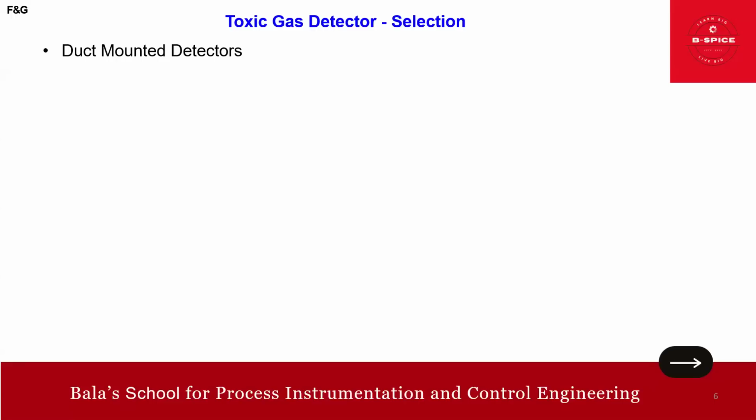So the duct mounted gas detector shall be provided complete with an integrated test gas facility. What for? To allow validation and calibration without removing the detector from the duct, even when the HVAC system is in operation. That is the point. So calibration of the duct mounted detector shall be possible standing on a fixed floor, although the detector is much higher. Or maybe we can also have it higher. So yes, that's all about this.